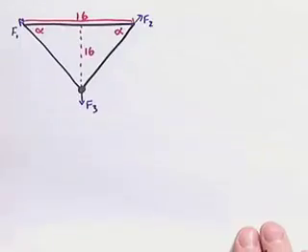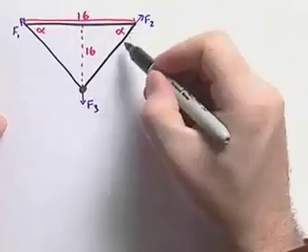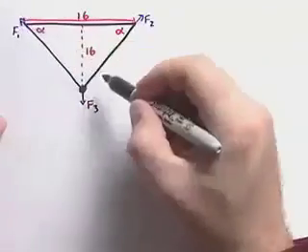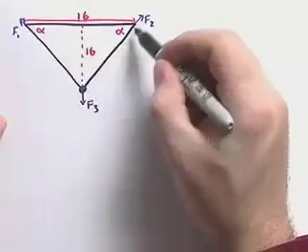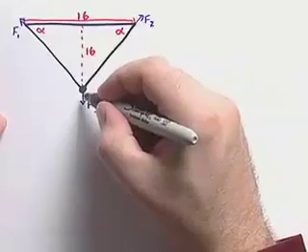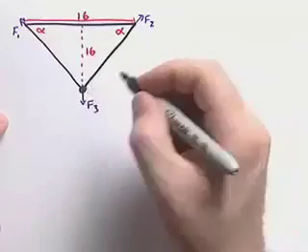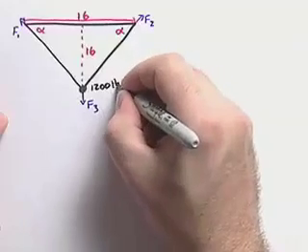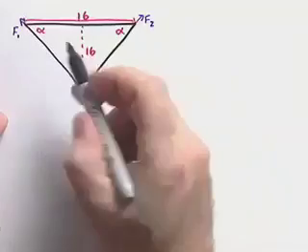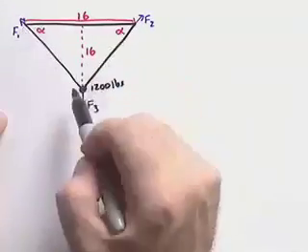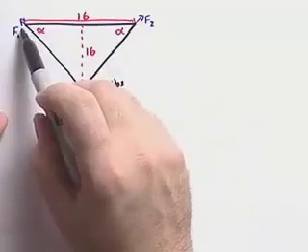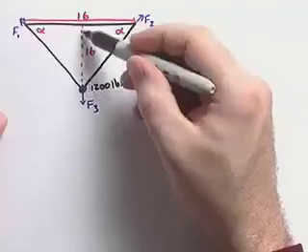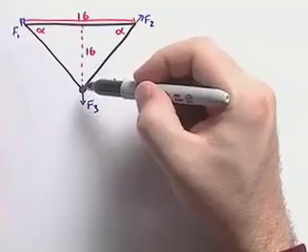I'm going to go ahead and draw a diagram here where we have some forces. We've got force 1, the cable going in this direction, force 2, the cable going the other direction towards the ceiling, and then force 3 is going to be gravity. The weight is 1,200 pounds. And we'll imagine this is our chandelier. The cables are attached to the ceiling at a distance of 16 feet apart along the ceiling, and the chandelier is hanging 16 feet below the ceiling.